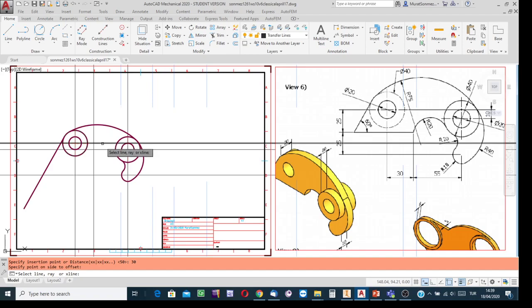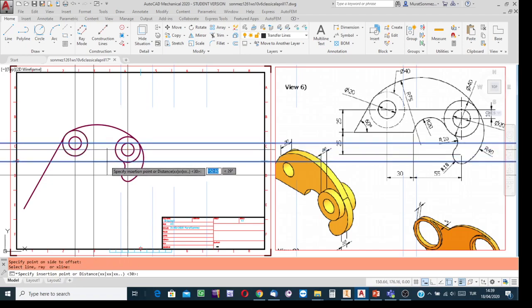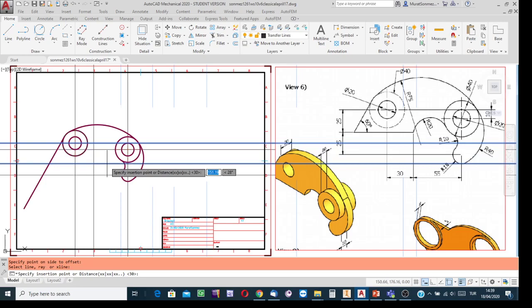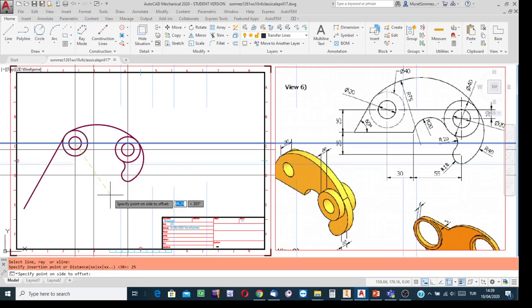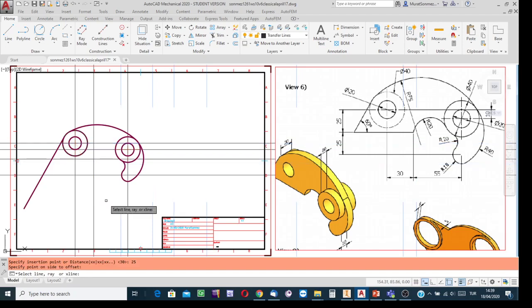And then the other transfer line is relative to this horizontal transfer line. It passes through the reference point. Indicate and write the coordinate value 25. Press enter, and then I know that point is at a lower level with respect to the center. Move the cursor in the down direction and click. Here we are. This intersection, no doubt, is the terminal point.